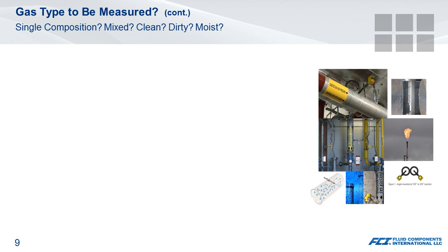A little more on gas composition. I would add, if your gas composition is going to change, you need to specify that to the manufacturer. What is the composition now? What could it change to? Those percentages, by how much? And then whether it's predictable and repeatable.